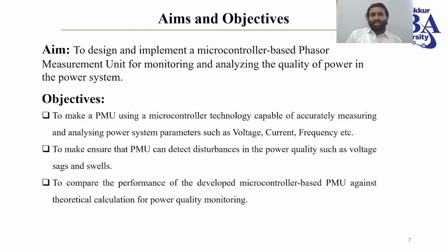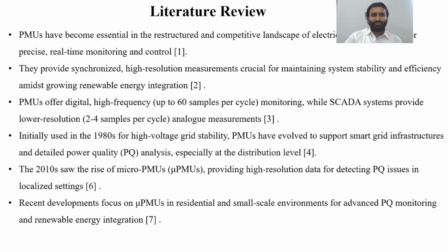We also want to make sure that the PMU can detect disturbances in power quality such as voltage sags and swells, and most of our work is on voltage sags. You will see this further in our presentation. Then we compare the performance of the developed microcontroller based PMU against theoretical evaluation for power quality monitoring. We use some mathematical models and embed them in our microcontroller, then we compare the results of our PMU with the mathematical calculations.